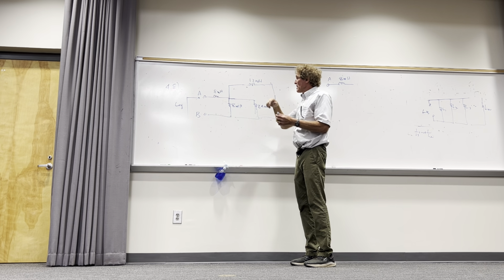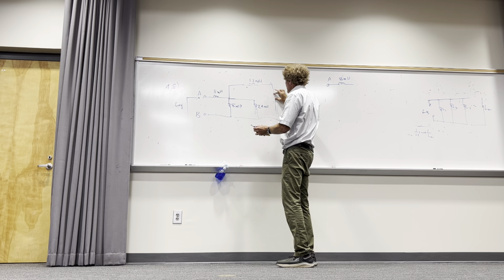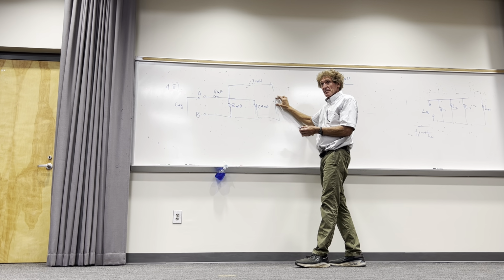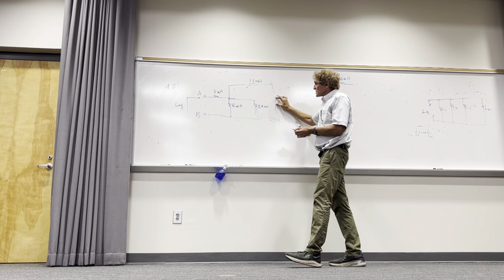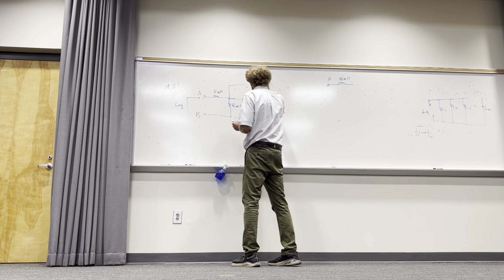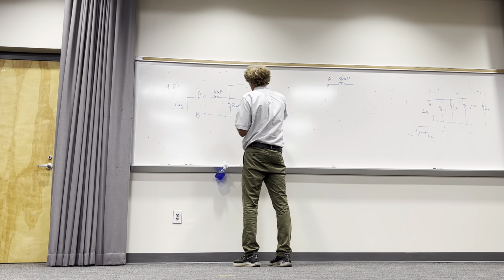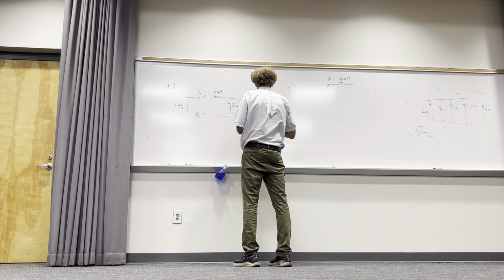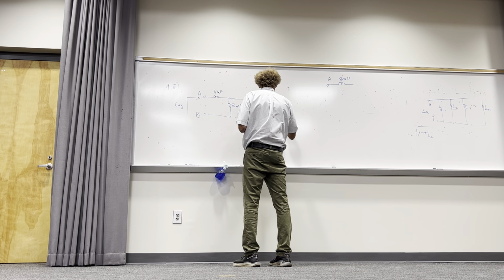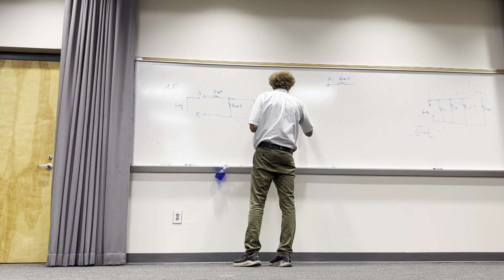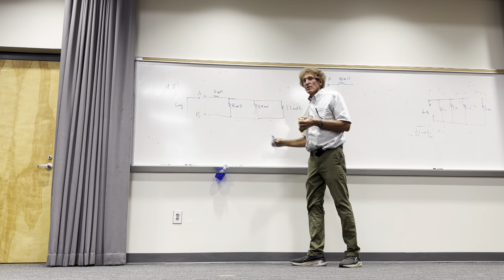Take your moment. Remember, I can take this and slide it this way if vertical helps you, right? They're all in parallel, right? So I have 12 here in parallel. I'm going to get rid of that. That's done just to make sure the topology doesn't bother you. So that's 12 millihenries. Well, what would that equivalent be?